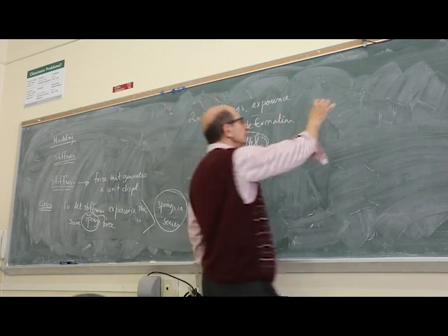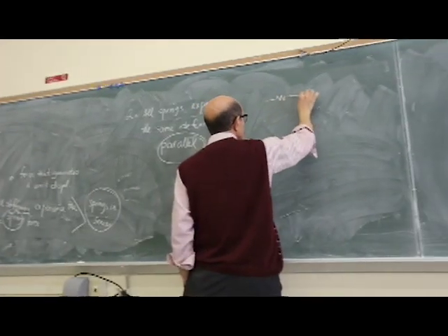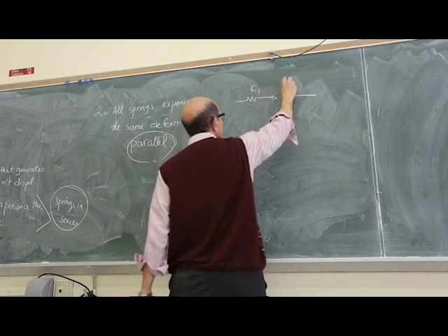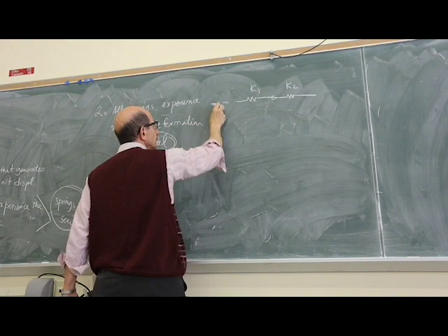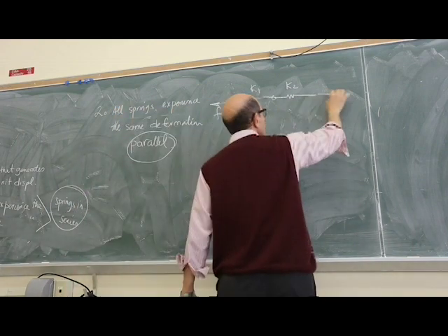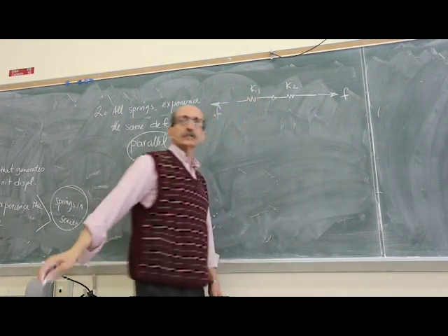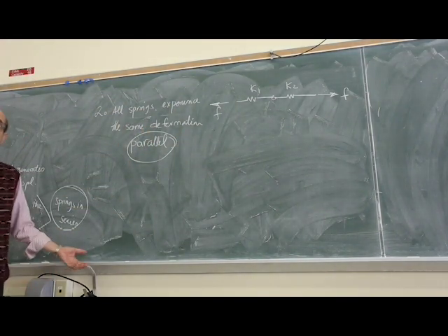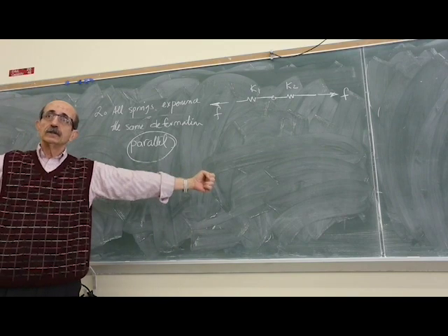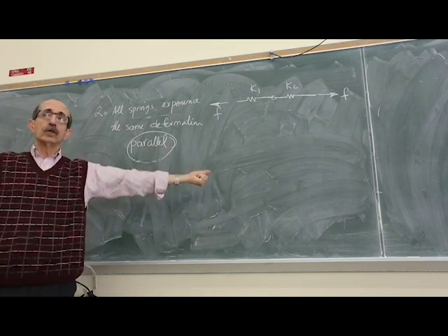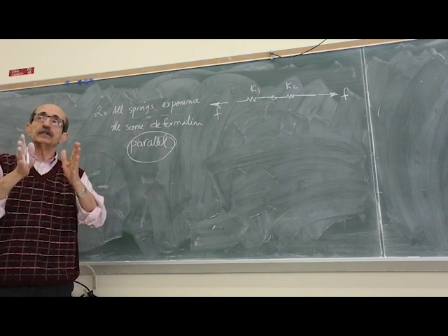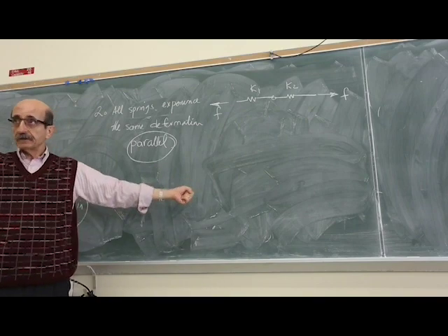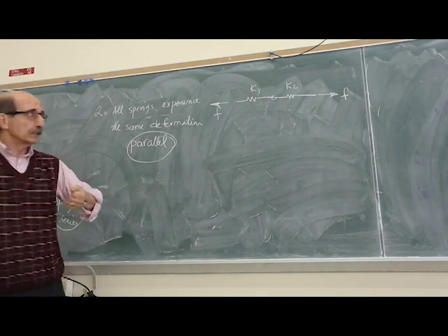So case one means this. Let's say, to start with, you have two springs with different stiffnesses, but they are subjected to the same force. Obviously, each spring goes through different deformation. You have two bars connected with each other, subjected to an axial load. Each bar, depending on its geometric and material properties, will elongate differently than the other one.